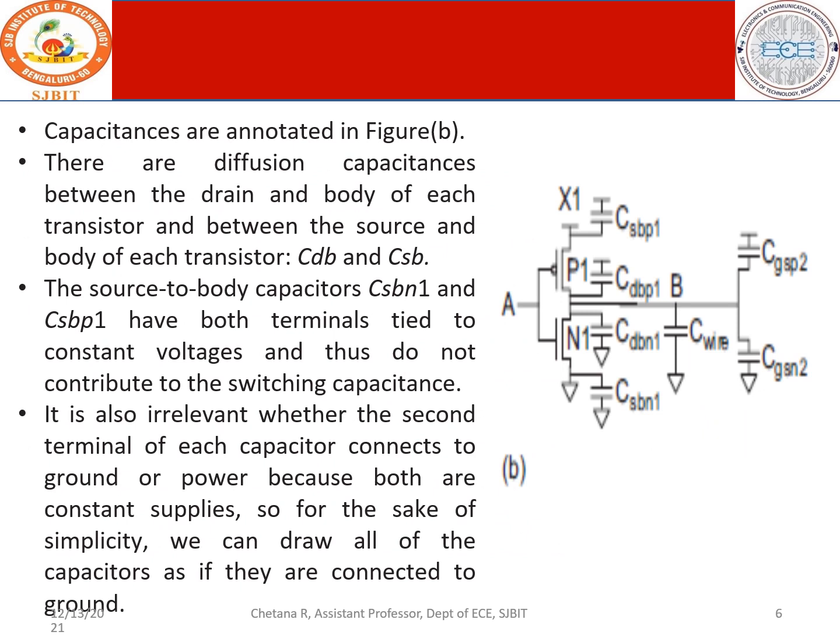So this is how the representation of a diagram looks. Here the capacitances have been shown. When you have a transistor, there are three terminals: one is the gate, one is the source, and the other one is the drain. Similarly, in N-type, you have the drain, the source, and the gate. So these are the capacitances annotated. Now we have something called diffusion capacitances. Source and drain are nothing but at the diffusion layer. The capacitances at the source and the drain are called diffusion capacitances, and since it is with respect to source, it is suffixed as Cs, and B is the diffusion or the substrate body.